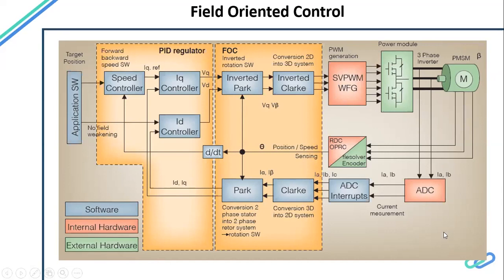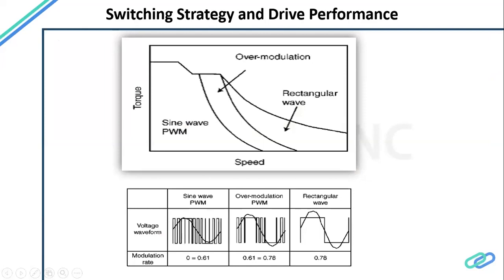We will be doing a deep dive on all these different elements that I am talking about now, and they all impact the overall machine. Okay, the speed. You see the speed here. We are very much limited by this topology. If we do some more modulation by injecting, say, third harmonic, we can do better and get maximum speed, right? So the same motor can behave in a different manner when we introduce this machine to different switching topologies. So as a machine designer or electric drive person, we should also look into these aspects.